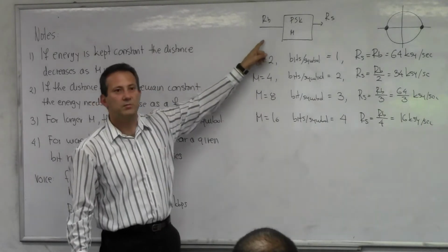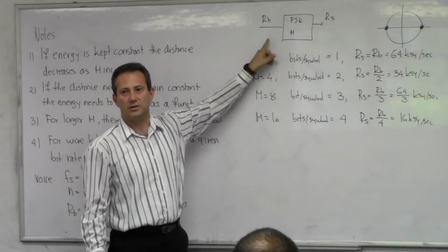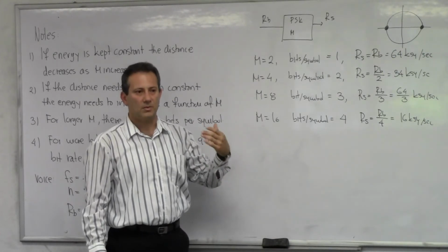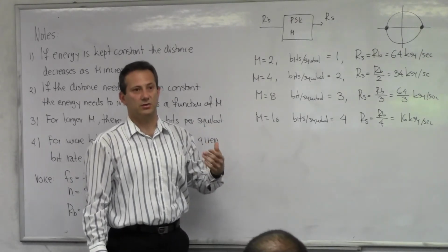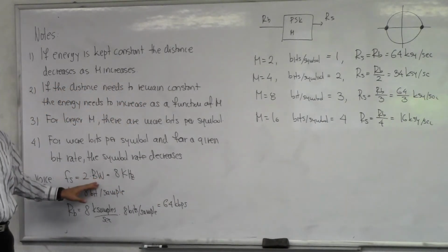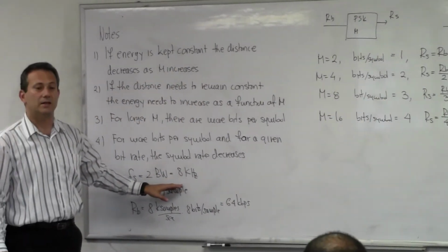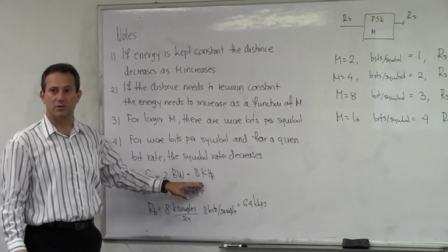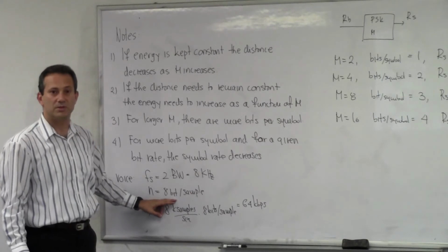On one end, you have the bit rate, which is kind of always constant. It comes based on what it is that you're actually digitizing. You're digitizing voice. So the voice has bandwidth of 4 kilohertz, sampling rate 8 kilosamples per second. To represent it with a good enough signal to quantization noise ratio, you need 8 bits per sample.